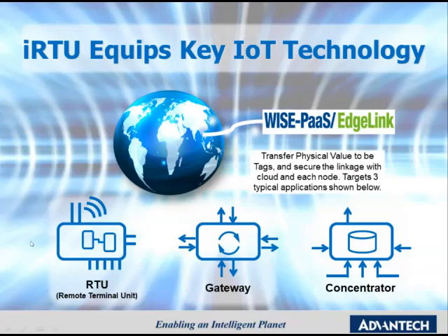same time. In RTU, it works as a traditional RTU to change the interface from different data, for example, from the serial to the Ethernet. And in the gateway, it changes the data between different protocols such as Modbus TCP, Modbus RTU, and MQTT. And when Advantech 3600 acts as a concentrator, it has the ability to calculate and process the data, and data to the cloud could be transferred from meaningless raw data into useful important data and then updated to the cloud to save the wireless bandwidth and fee.